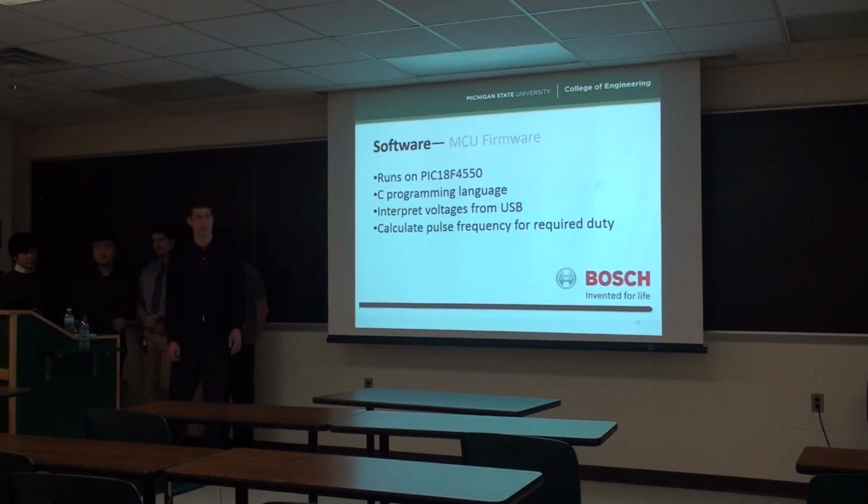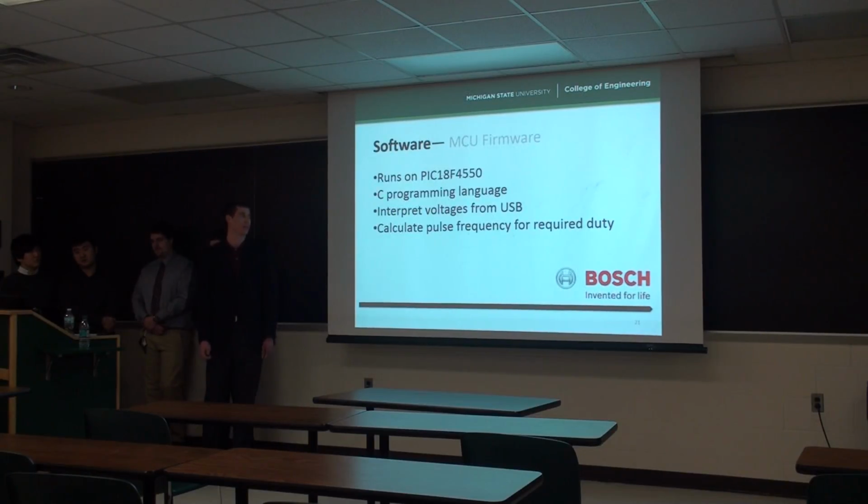Now the other side of it is the microcontroller firmware. As Chris stated earlier, we're going to be running on the same microcontroller as what we're using in lab, which is super convenient, and it's going to be written in the C programming language. Essentially, it's going to read the voltage versus time metrics from the USB connection, and it's going to calculate the pulse frequency to get the required duty cycle to simulate those waveforms.